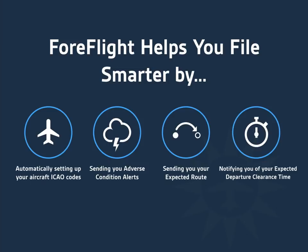If you're filing IFR, there's two great benefits. We can send you your expected route. So you file through ForeFlight. ForeFlight talks to the air traffic control system. There's a computer system. It's called ERAM. And ERAM, when it gets an IFR flight plan in, it says, that looks good. This pilot's going to be cleared as filed. Or, no, that doesn't look too good. We're going to have to amend this route. Well, because ForeFlight sent the flight plan for you, and we can listen in on that computer system, we know what ERAM is thinking. So if it's going to assign you a new route, we're going to push notify you that route. We're going to send it back to you so that with one tap, you can load it into Maps.